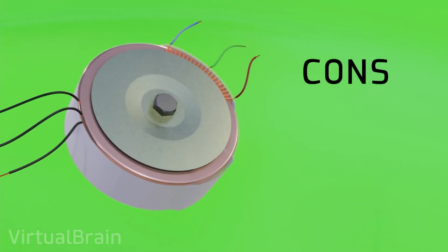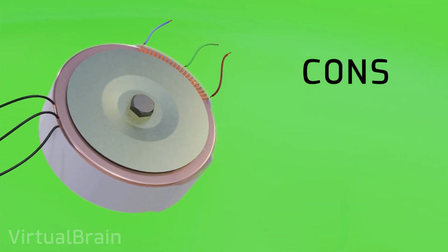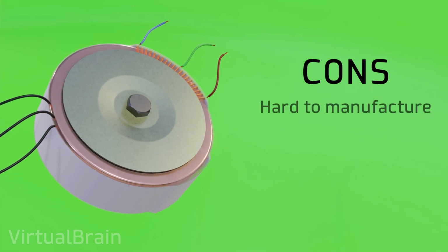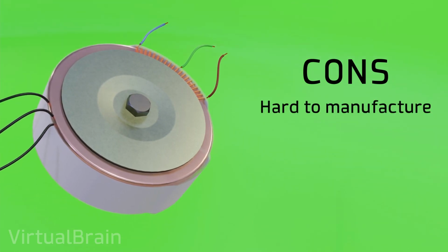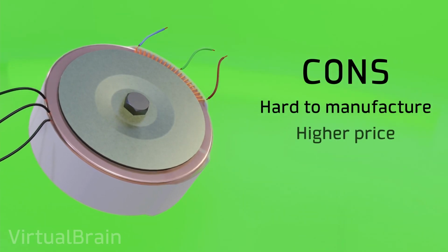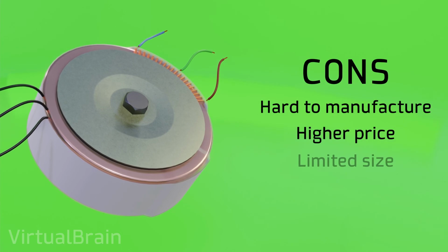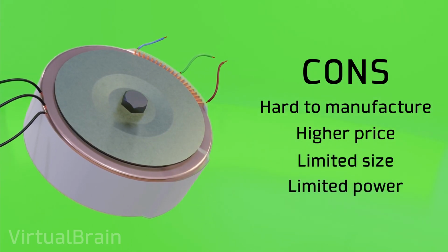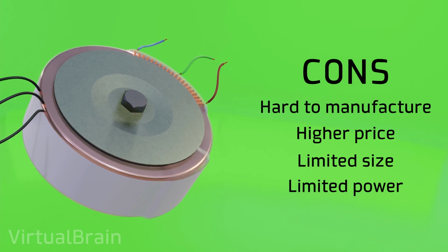Now that we understand all the benefits of toroidal transformers, the question is, why don't we use them everywhere? Unfortunately, not everything is perfect, because, due to their shape, these are usually more difficult to build than other types of transformers, which implies that they usually have a higher cost, and that generally they are not found in very large sizes, limiting the maximum powers to which they can operate to only a few kilovolt ampere.